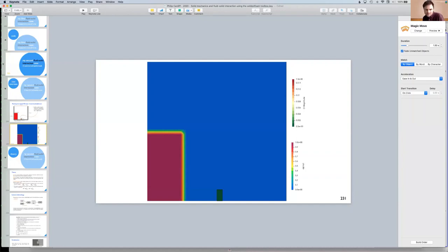The final question was, I wonder, is Solids4foam compatible with Overset? Yes, so Overset is available in the Foam Extend 4.1 version. There is Overset, is it icoOversetFoam, or whatever it's called. A port of that is available in Foam Extend 4.1, at least in Solids4foam when you compile it with Foam Extend 4.1. I haven't played with it too much, but in my experience, there's challenges with Overset, as with all of these things. So have a go and play with it.